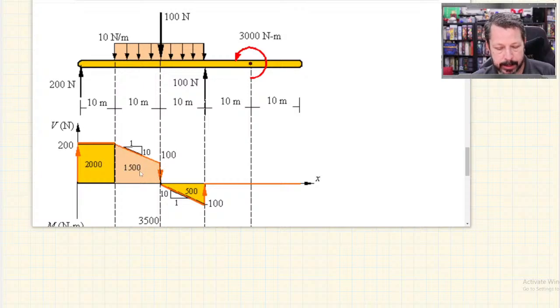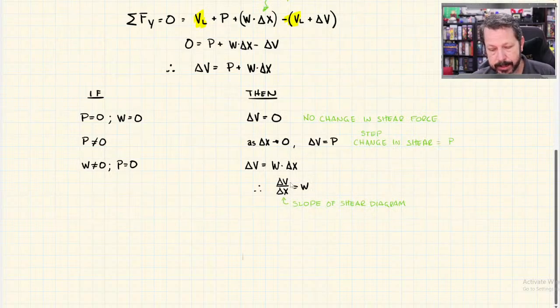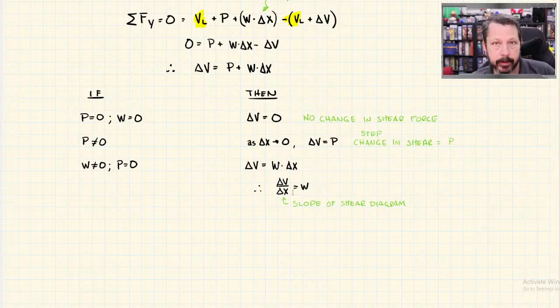Don't worry about these numbers inside the shaded area yet, that's for later. So we're looking at this 200 is the height of the shear, and it goes down, down, down to 100. So the total change over that distributed load is equal to W times X, however far it is that distributed load is existing. Okay. Oh, you're welcome. So thank you in the chat.